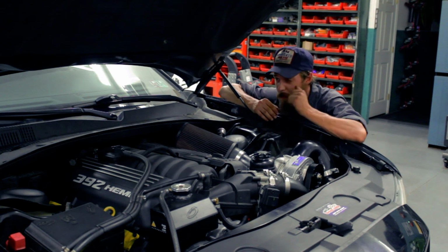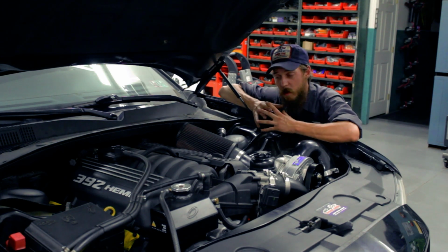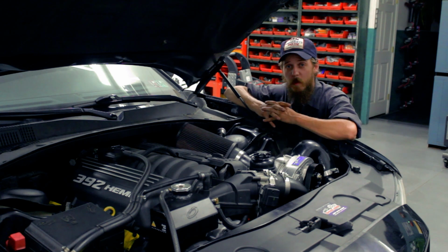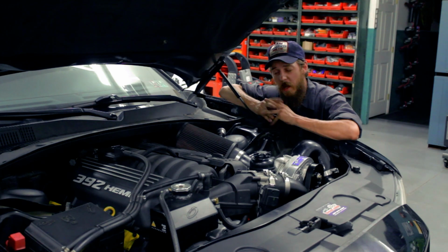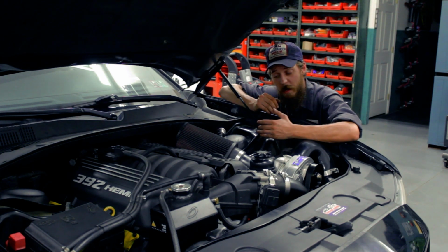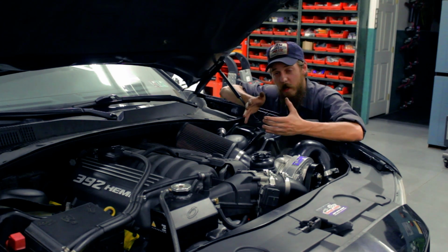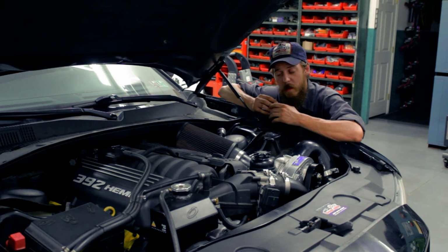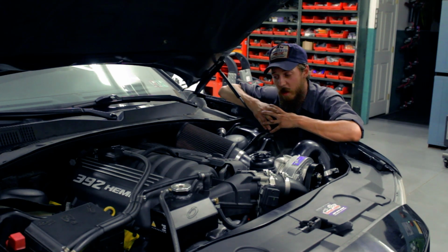I would say 2 to 4% of it would be scan data, going through scan data, seeing what agreed, what disagreed, finding data PIDs we did and didn't care about, and narrowing it down from a world of information to a manageable amount of information, and then cross-checking that against both our schematics and our service info and what we actually saw in operation. We may interpret service data this way or that way and see a different interaction in real life, so that's something to keep in mind as well.